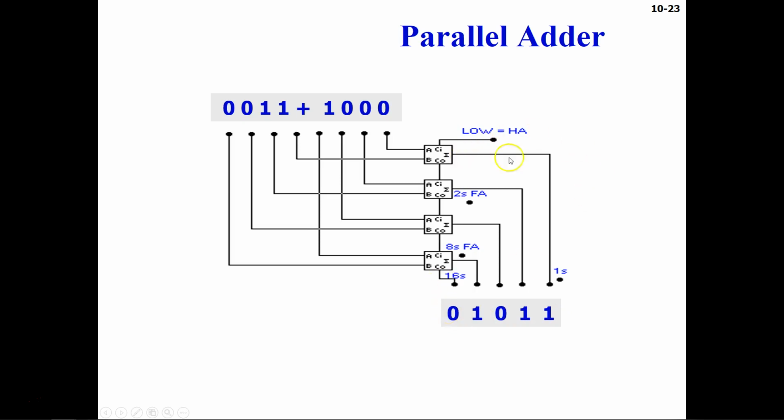The least significant bit in this particular case represents your sum from the first adder, and the most significant bit represents your carry out. This is your carry out, and in this you will have to feed some carry in into the circuit, because in this one we are using all full adders.